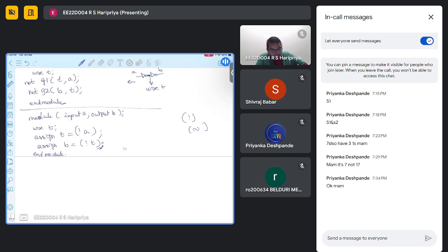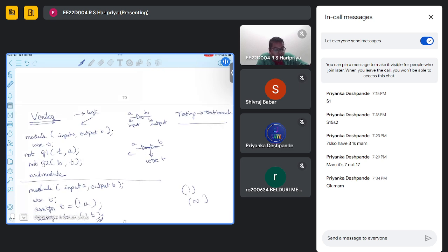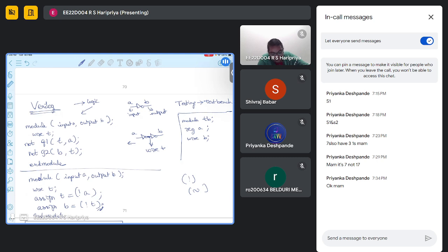Okay, so similar to this, if we want this value to be stored, say in some flip-flop, here comes the keyword reg, and these things we will see later. Now if we want to test this, that means we want to apply some input patterns. So our module is a test bench. Inputs we need to store, so we define them as a reg A, and outputs we are just observing, so B, and we have to call this module. Okay, so here one small correction.